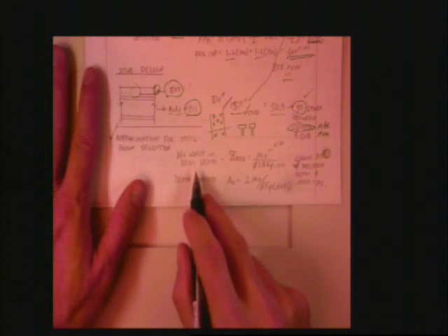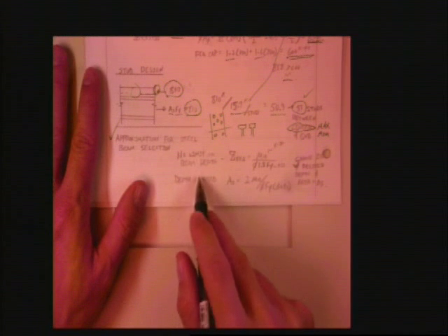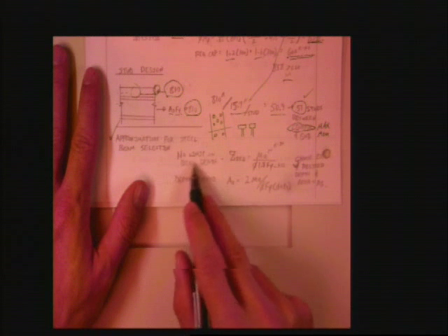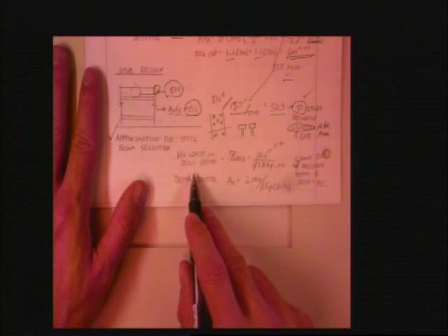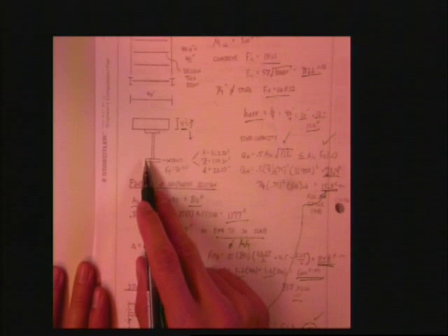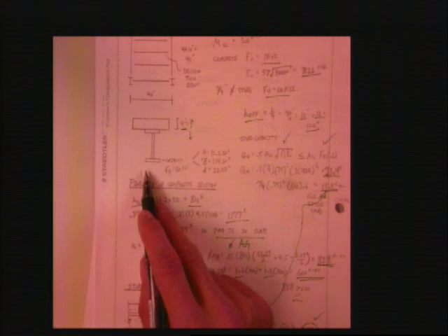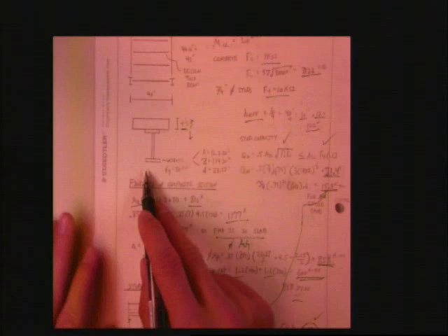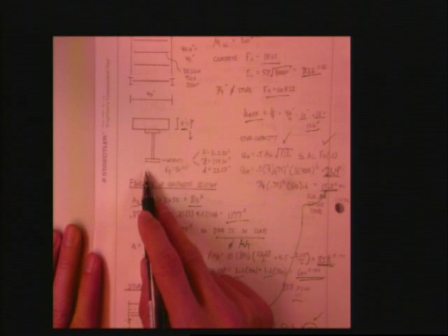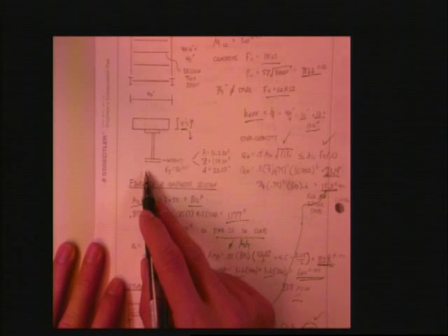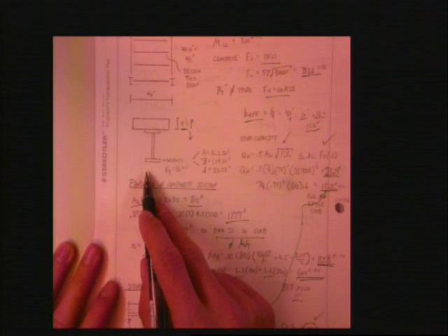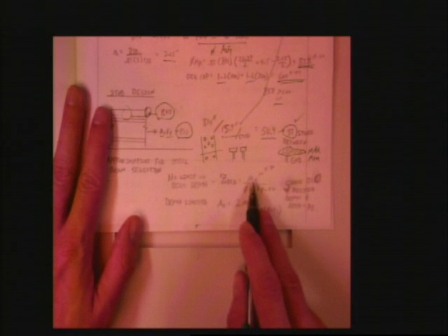So, if I'm doing a composite girder that has no limit on the beam depth, I can make this beam as deep as I want to. It doesn't happen much in life. Oftentimes some architect doesn't want it to be too deep. Oftentimes some hydrologist, if you're doing a bridge, has a 40-year flood or a 100-year floodplain. They don't want the bottom chord to intersect the 100-year floodplain. Or you have trucks that have to drive underneath it, so you're constrained on your depth. But if you're so lucky, you put your maximum moment in, and it's amazing how accurate this equation is.